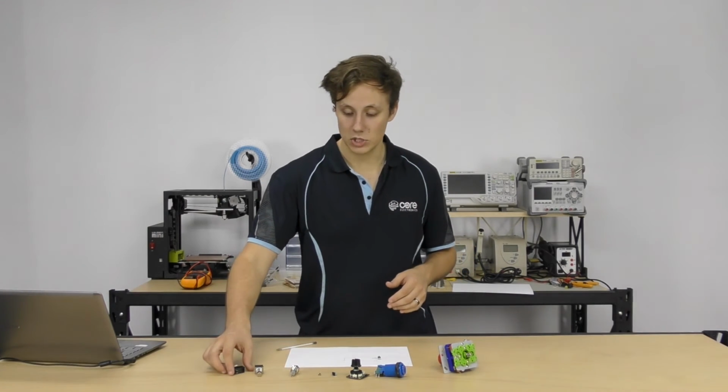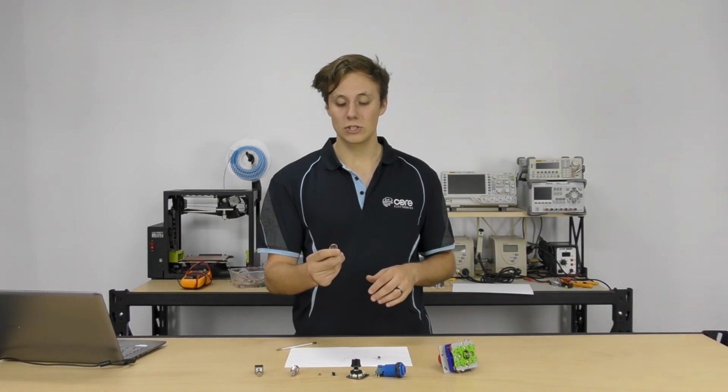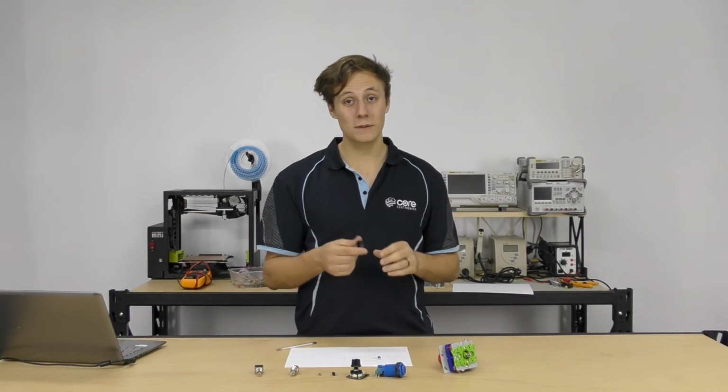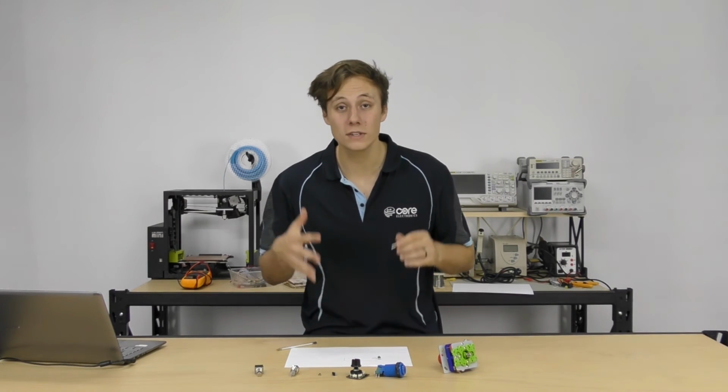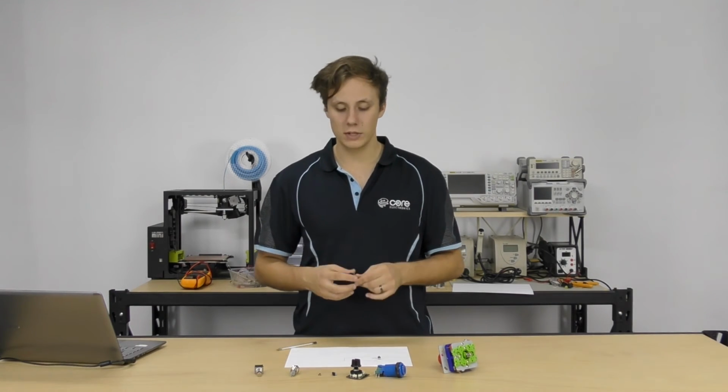Now, the bigger the switch, the more momentum that the contacts are going to have. Take this switch here. This guy is rated for mains voltages, which means it needs to be able to handle 2 amps at 250 volts. That's 500 watts of power. That's a lot of power, people. That's as much power as a typical desktop computer would consume, and that's a decently powerful one as well. So the contacts in here are going to be big and heavy. They have to be rated for that kind of current, otherwise they're going to get too hot and melt the plastic or destroy the entire mechanism. So that's why you pay attention to the rating.